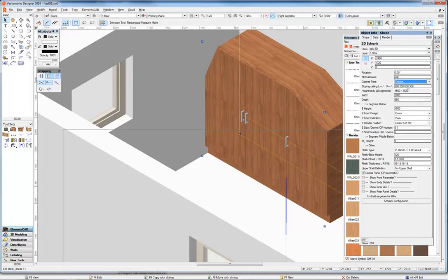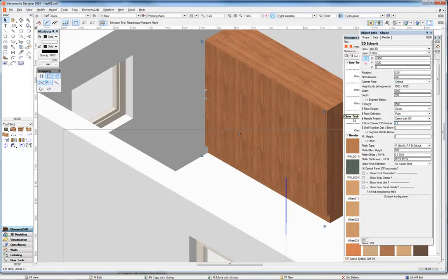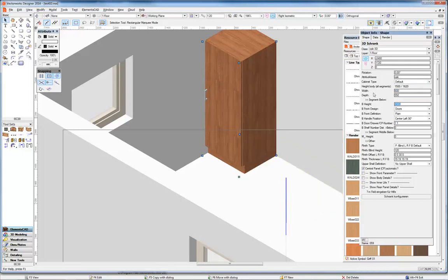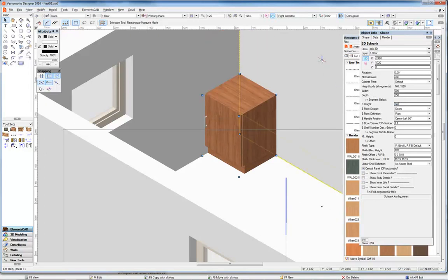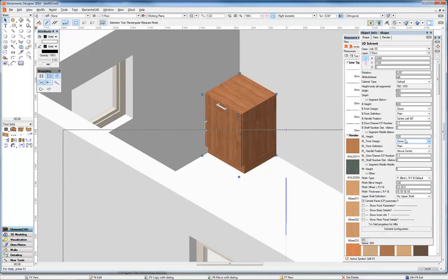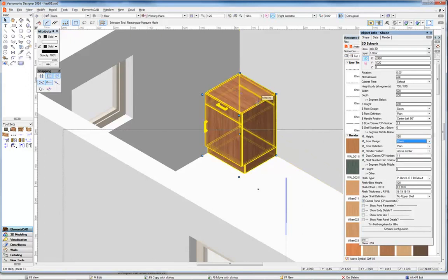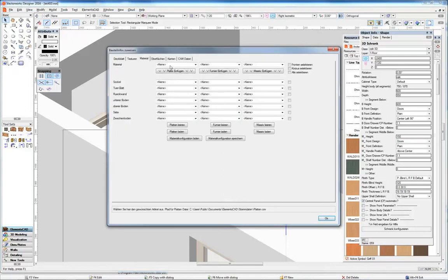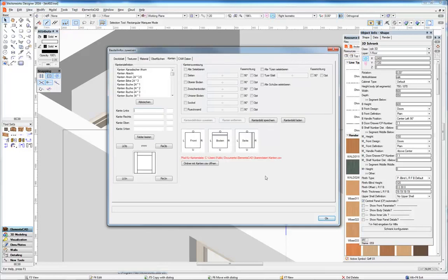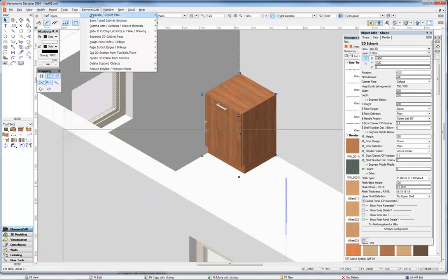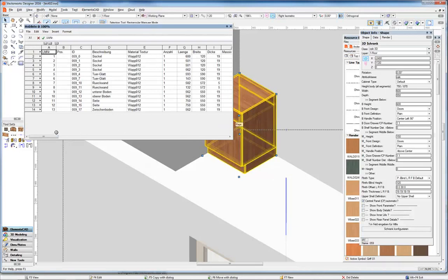Well, I go back to a default cabinet. Make one door and go to 600 millimeters and 740. Now I define a second segment with 150 millimeters, and here I can define doors or drawers as well, lines, something like this. I make a double click and go to the further tabs, and here I can assign materials for the cutting list, and I make entries for each panel, and I can define edges here. And finally I can go to cutting list and define a cutting list, and here I see the result, and I can copy paste it directly to Excel, for example.